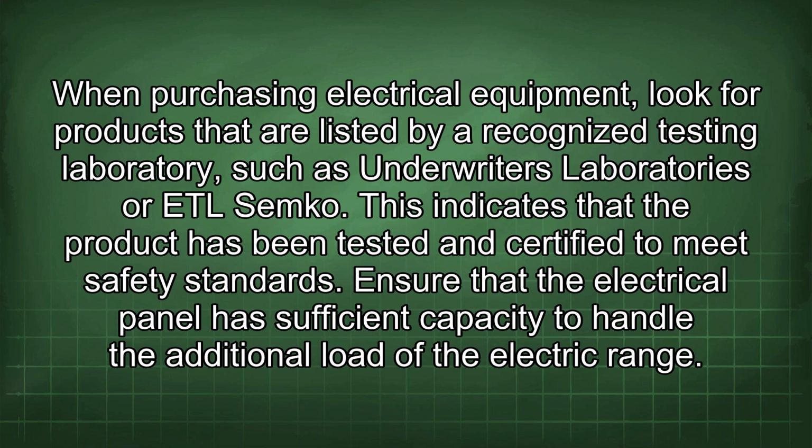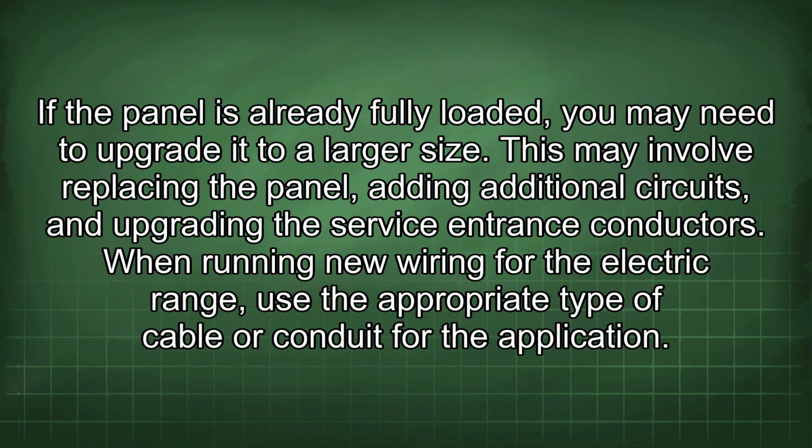This indicates that the product has been tested and certified to meet safety standards. Ensure that the electrical panel has sufficient capacity to handle the additional load of the electric range. If the panel is already fully loaded, you may need to upgrade it to a larger size. This may involve replacing the panel, adding additional circuits, and upgrading the service entrance conductors.